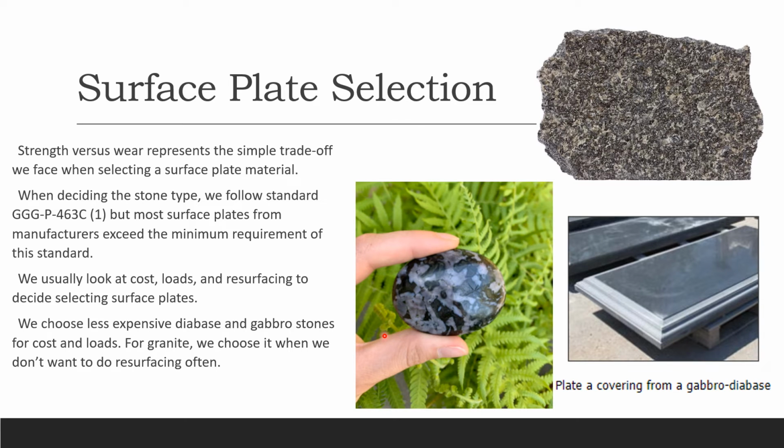So we choose the less expensive diabase and gabbro stones for cost and loads, and they can also carry heavy loads. For granite, we choose it when we don't want to do the resurfacing often, because with these two stones, you have to do resurfacing.